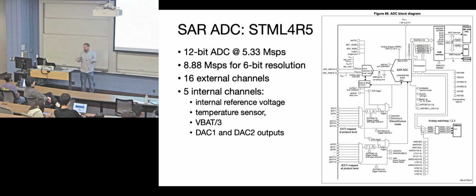For what you guys are doing, it probably doesn't matter. Nobody cares. But in a world where you're trying to make really accurate ADC measurements, you either cannot be doing ADC while you're doing SPI transactions, because you'll actually see the noise from your SPI in your ADC values, or you have to use a different reference voltage.